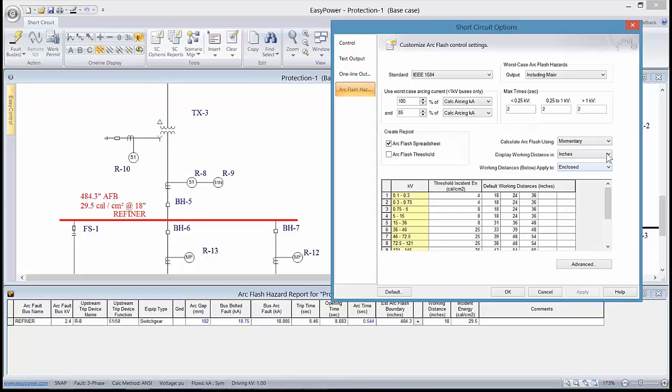And the reason for pointing that out is if we were looking at the interrupt rating or interrupt current, it would be lower because some period of this arc is going to happen beyond the half cycle. I guess what I'm trying to get at is the most accurate calculation is actually the integrated mode, which allows us to take that part of the fault current which occurs in half a cycle, plus that part of the fault current which occurs in the first 5 cycles, plus the lesser that occurs beyond that in the balance of the 30 cycles, and adds it up.